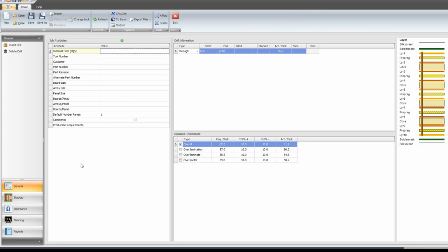You need to fill some of these things in to get the processing to work, and it's also used for different parts such as import and to other systems and for rules driving, but not super relevant to the stackup itself. 18 by 24 is our standard panel size. We build anything that we think is buildable on that. So the exceptions would be exotic materials, materials with very high scale, or just very expensive materials where the customer doesn't want the part that big.